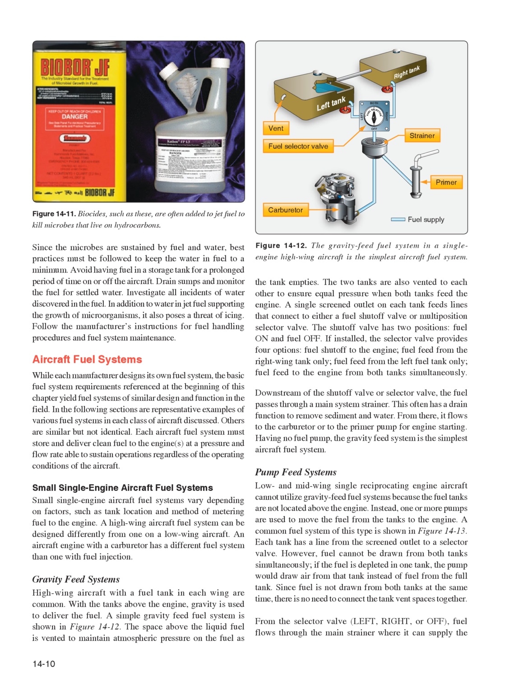In addition to water and jet fuel supporting the growth of microorganisms, it also poses a threat of icing. Follow the manufacturer's instructions for fuel handling procedures and fuel system maintenance.